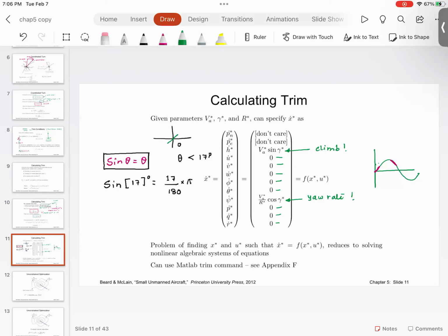The only difference is, depending upon the operating region, this linear model will be good or that linear model will be good. So what you do is you design controllers depending upon those different linear models. And that is called gain scheduling. You have a different gain when the aircraft is at this operating region. You have a different gain when the aircraft is in another operating region. That's all there is to gain scheduling.